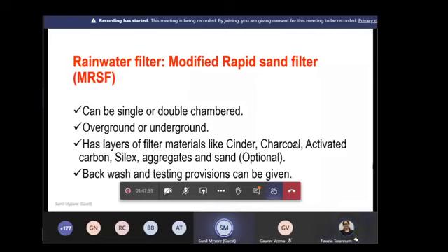Here you put rock, activated carbon in a large bed and make the water flow through that. We have tested a lot of samples. Input to output, there's a significant difference. I'll share those details with you a little later. But yes, in a place like Delhi, there will be atmospheric pollution where you need a kind of filter. The best thing is to use activated carbon.